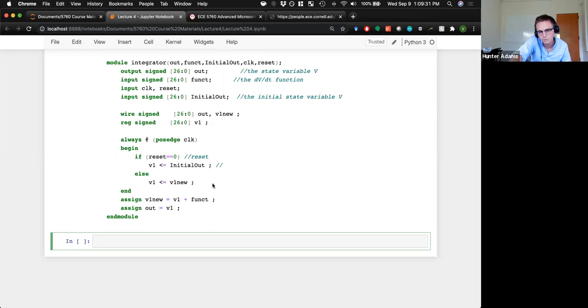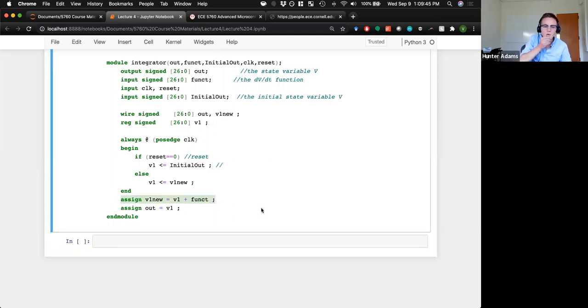So this will ramp up and then it'll ultimately overflow and ramp up again. So your integrators will look a lot like this. What will likely be different is this line. You will likely have your integrator module tied potentially to some separate module that's calculating. You might not do it this way, but the way I expect many of you will do it is have a separate module that's constantly calculating derivative values and tying the new output of your integrator to that separate module. But structurally, your integrator will look like this.